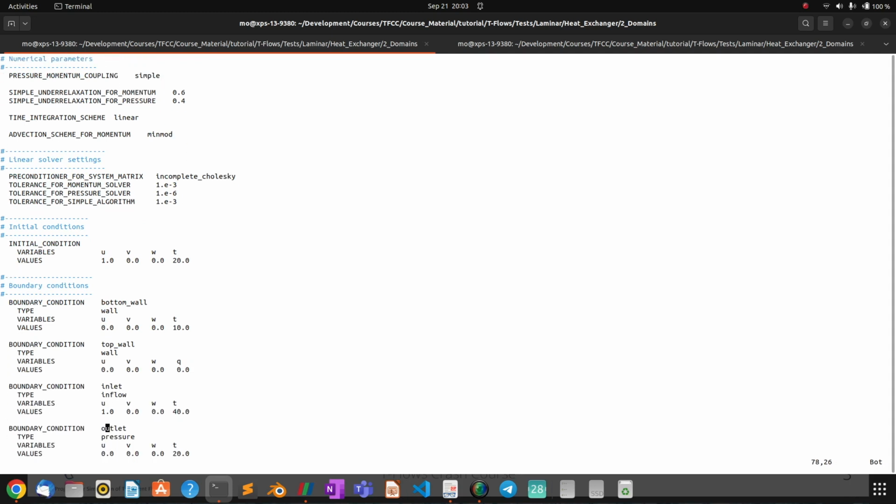So if we go to the inlet, we want to specify passive scalar 1, which will take the name C01, let's say, and then C01 will have a value of 0.01, for example. And then C02 could have a value 0.02.